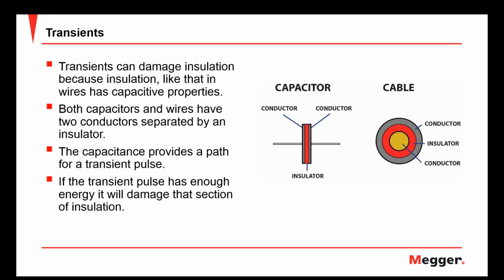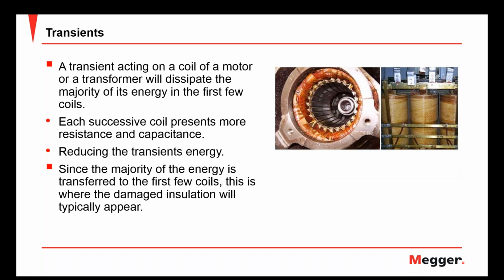As you get transients that occur, what they're doing is they're rapidly changing the difference potential across those conductors, or across the insulator, I should say. So you get a momentary pulse that goes through, and it will over time break down the insulator. And as the insulator starts to break down, its impedance in that section where it's breaking down is getting lower. So as you hit it with more transients, what ends up happening is that same area starts conducting that electric pulse, and it will break down over time, and that's what wears down these insulations. That's why transients are so bad for it.